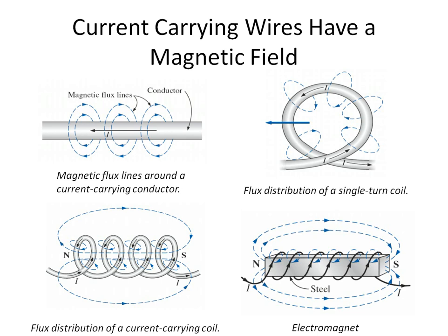An electromagnet is made in this exact same way, where a piece of steel or soft iron is surrounded by a coil of wire and then current passes through it. The steel concentrates the lines of flux and makes a very strong magnet. But since it is dependent on the current flowing through it, it is an electromagnet. And when the current stops flowing, the magnetic field disappears.